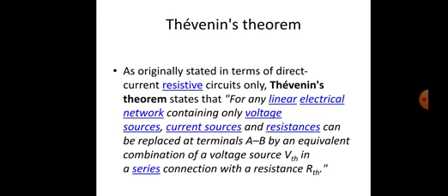According to the Thevenin's theorem, any linear bilateral network, irrespective of its complexities, can be reduced into a Thevenin's equivalent circuit, having the Thevenin's open circuit voltage VTH in series with the Thevenin's equivalent resistance RTH along with load resistor RL.